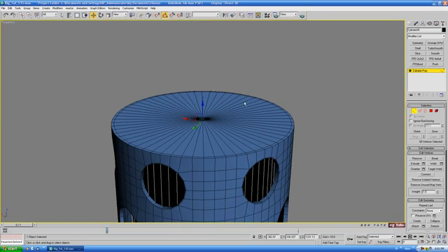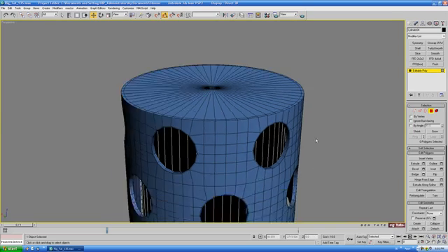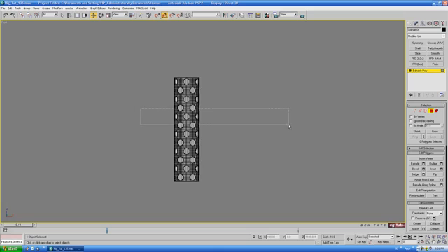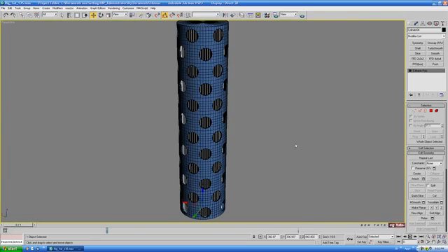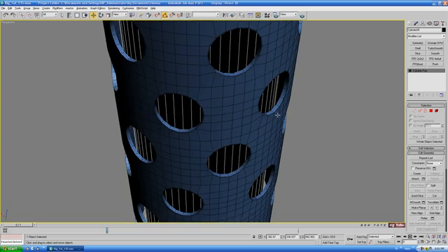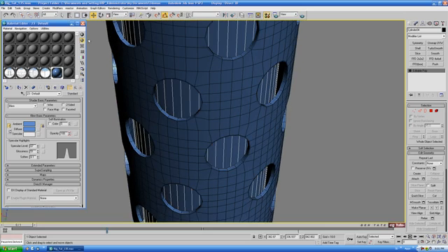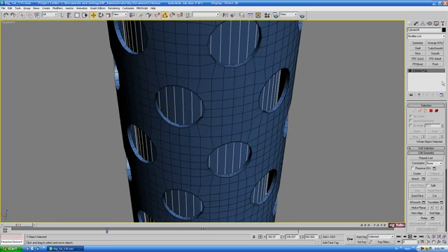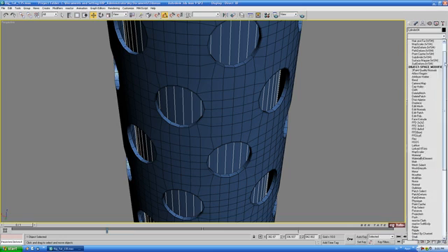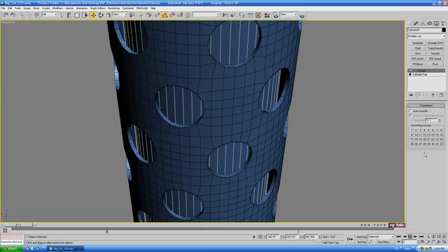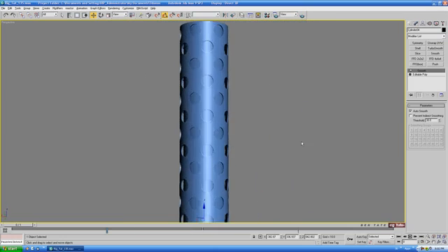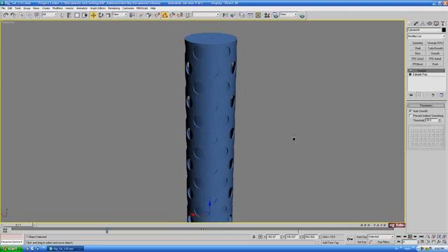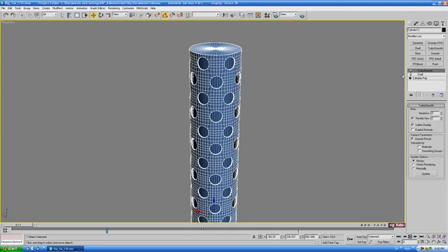And because the top's capped with this piece here, we can delete the top and bottom polygons. Okay, so just drag right through the side polygons, hit Control I, and delete the 2 caps. Okay, let's put our shader on that one. And I'm also going to put a smooth modifier on for good measure here. So grab a smooth, let's hit auto smooth. Okay, and let's just see what it looks like with the turbo smooth back on here.